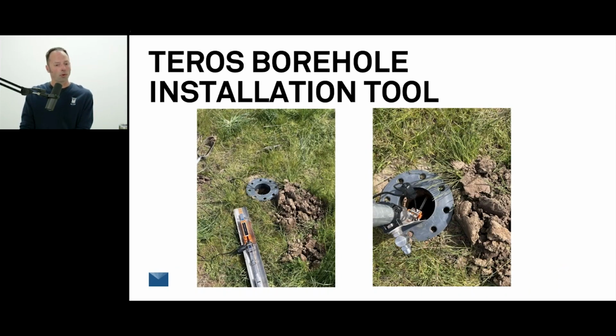So you're digging out a borehole. In this case, this tool uses a 4-inch borehole, and we've got a nice little kind of placer at the top of the hole which you can use to make sure you get your sensors in a line or even find a pilot hole later.